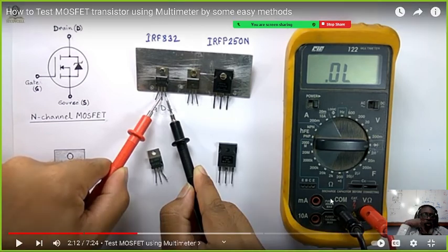And how do you think you'll turn it on now? You have to put a positive to the gate, don't you? How do you put a positive to the gate? Like a DC, put a voltage. A DC, alright. So we can use the tester right here to do that. The positive is the tester lead.